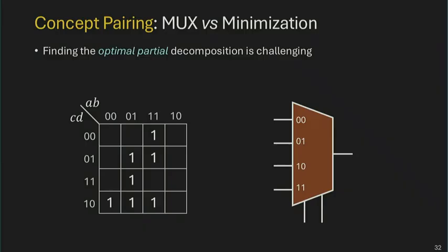And given this circuit, I really don't know how to cut it, how to find the best cutting. I'll probably try this first. And then this one gives me like 1 gate, 1 gate, 1 gate for a single 1 or 3 ones. I need to represent that subcube, 2 by 2 K-map as a Boolean expression. So I need some additional gates. If I do cutting in a different way, let's say cut here, cut here, cut here.